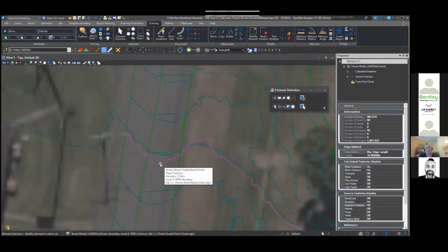So there's a lot more points that's incorporated into the digital terrain model, and therefore the contours are less rigid. There's more flow to them. Additionally, with the other contour that's shown there that extends to the left out there, that's part and parcel of the LiDAR data from Geoscience Australia, or that point cloud data that we created.